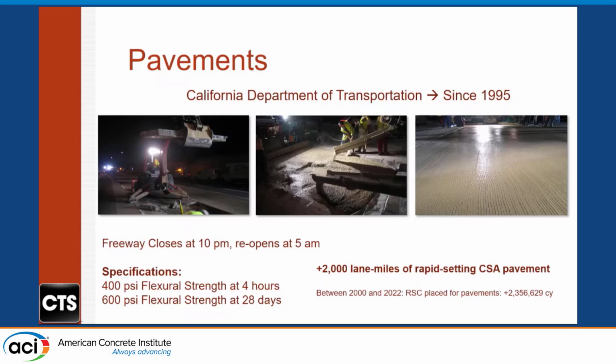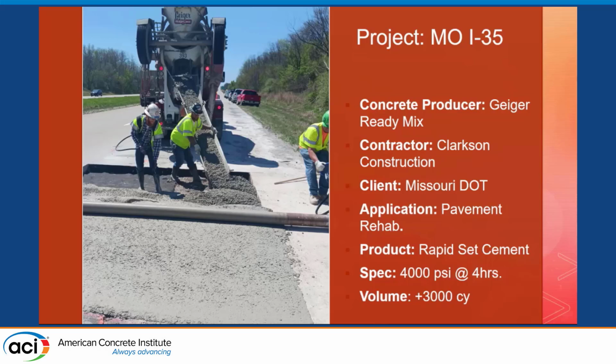The main spec is 400 PSI in flexural strength at 4 hours, 600 PSI at 28 days, or 550 sometimes, depending on which spec. But that's the state that uses the most, and from there, many others adopted the technologies. Again, I can pick many. I was just involved in this one last year in Missouri.